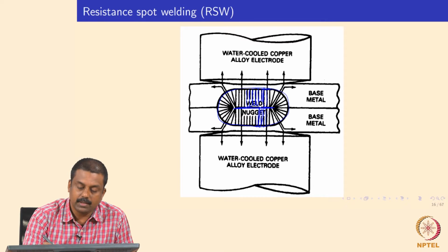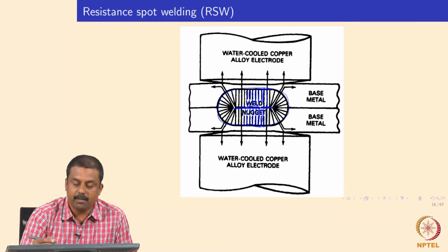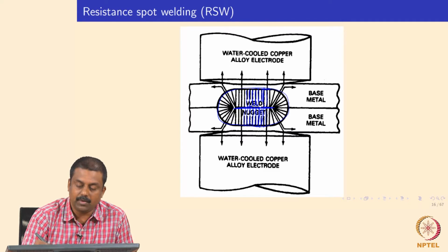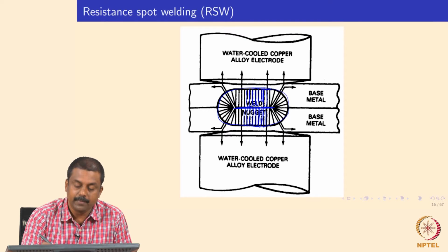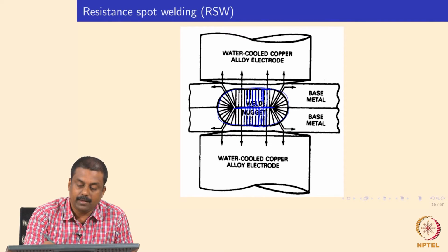This structure is not metallurgically preferred because of the very strong segregation that develops during solidification of the columnar grains. During this process, alloying elements prefer to segregate to the liquid, and they end up enriching the solidification grain boundaries as well as the weld center line.